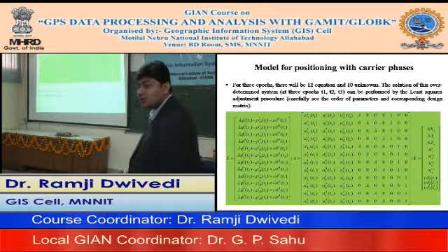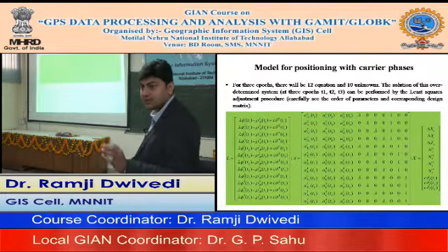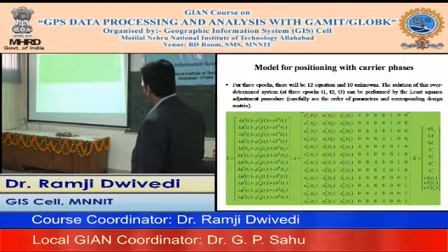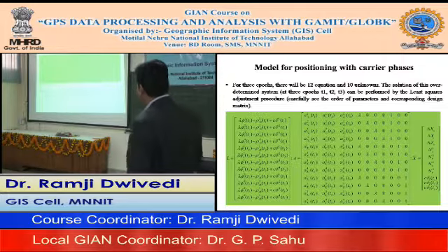Your receiver is not in a position where it is moving, it is static, so that's why there is no variation in this term with respect to time, because we consider the receiver here as static. Unless you lose the lock, your value of N will not change. So obviously the term which will increase in terms of unknowns will be the clock offset.